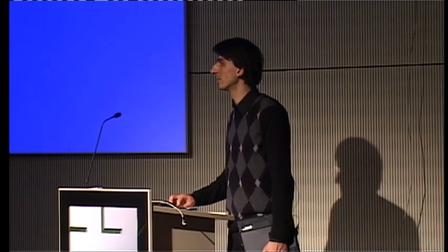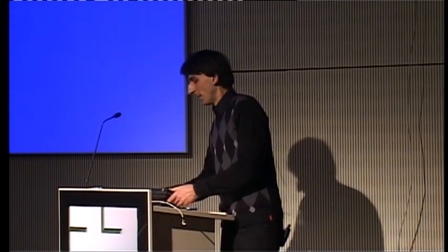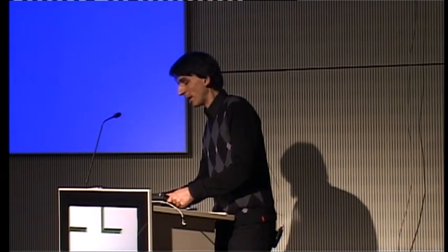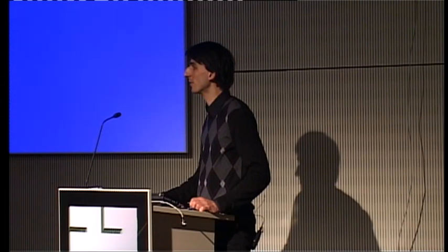Can you use DMA to refresh the controller? No. This is a very primitive microcontroller. There are some of them I haven't looked at though, where they claim that they can support shared memory configurations. I hope nobody in the PC segment has been crazy enough to hook up an embedded controller for a laptop in a shared way to the same memory that the host CPU is using.